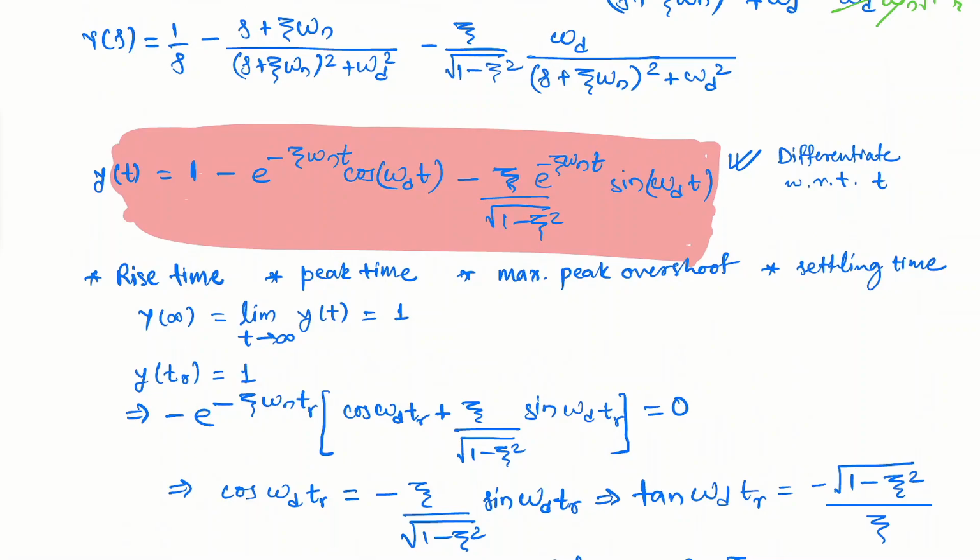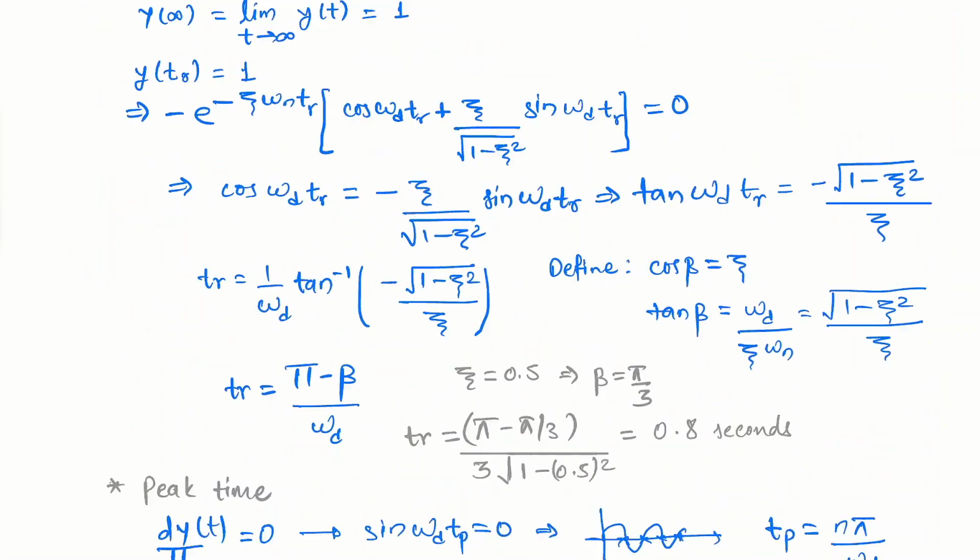However, when we define settling time, we are saying that if we are within 2% or within 5% of the steady state value, and we have reached that band for the first time, and given no change in the input, we would stay in that band forever. Then in such a case we can say that the output has settled.